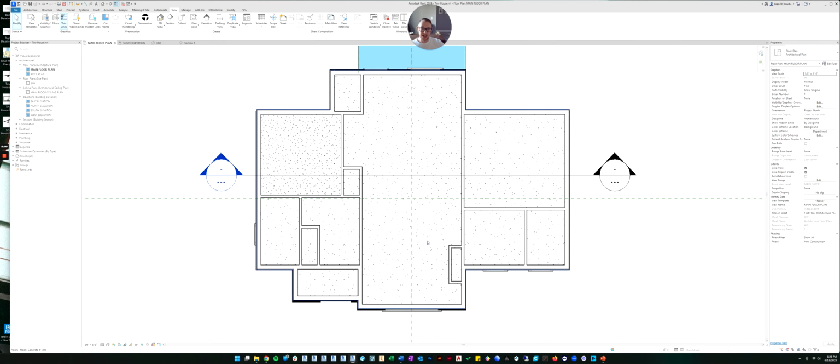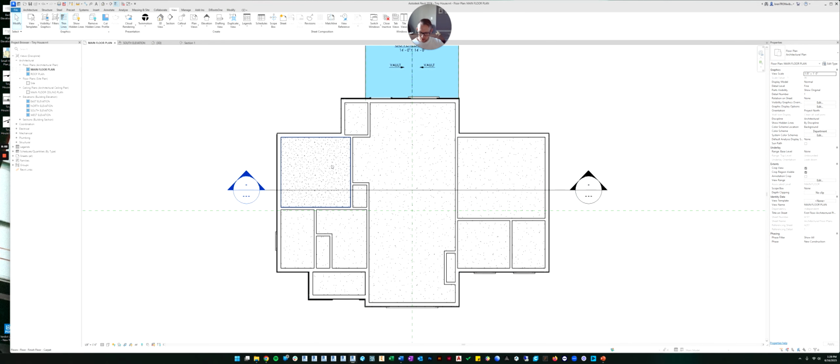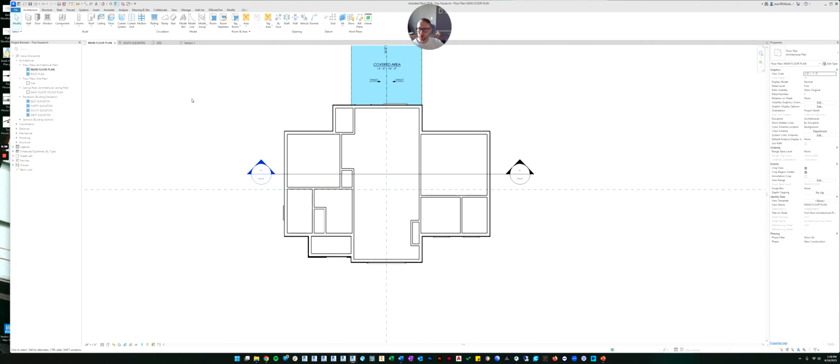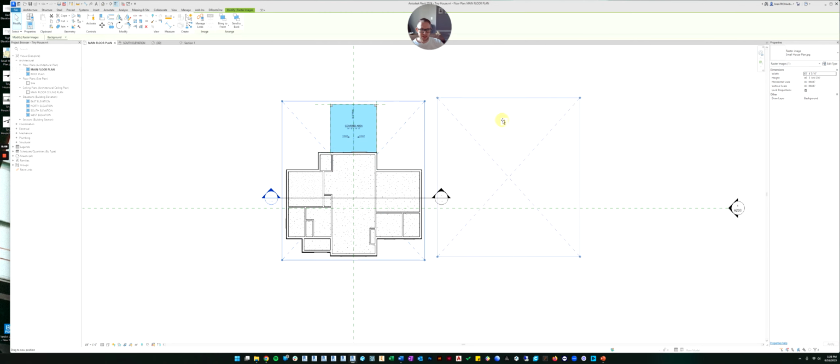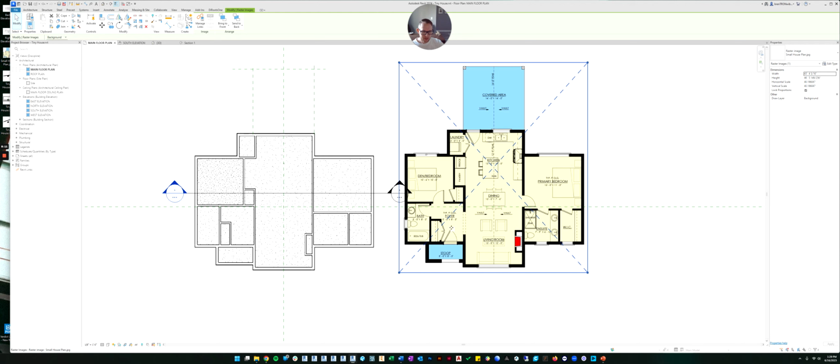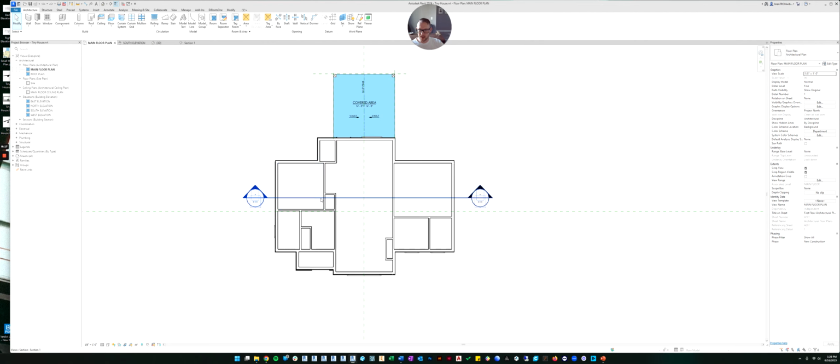So now let's put in tile. So what we're going to do is we'll go into the floor command. And I don't remember which one of these rooms is a bathroom. Let's move this over. The bathroom is here. Okay, so let's do this floor. I'm going to Control Z and take that back over there.